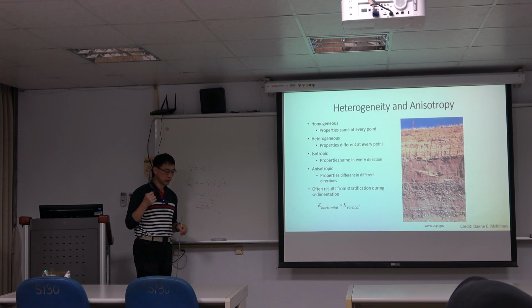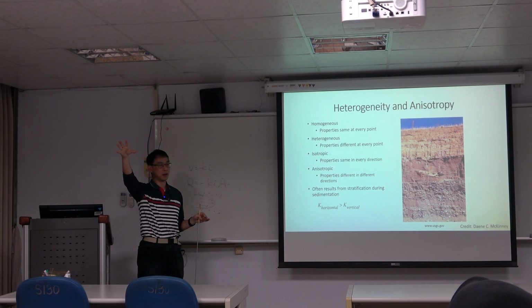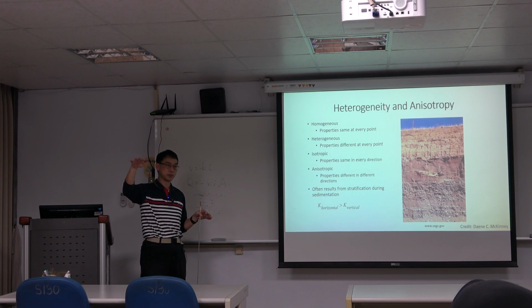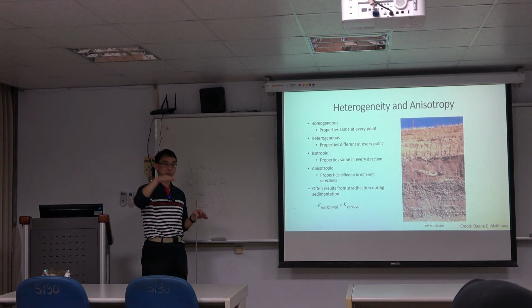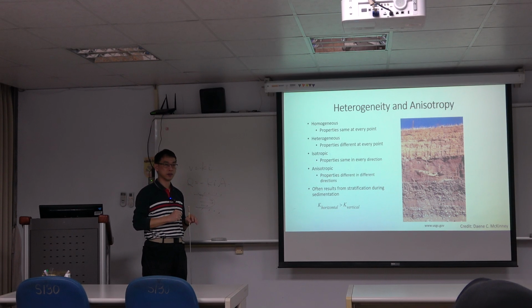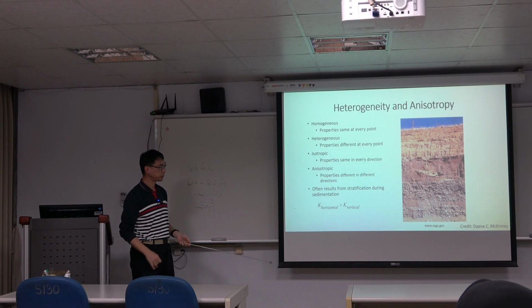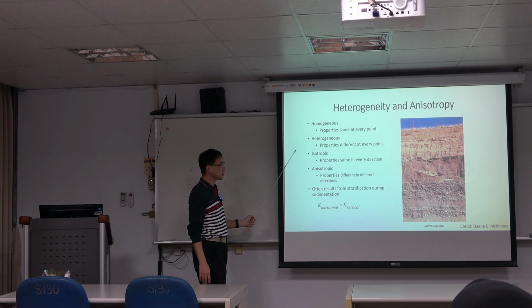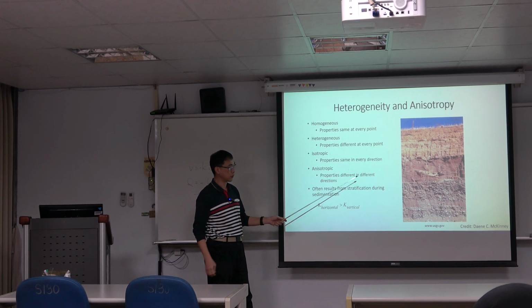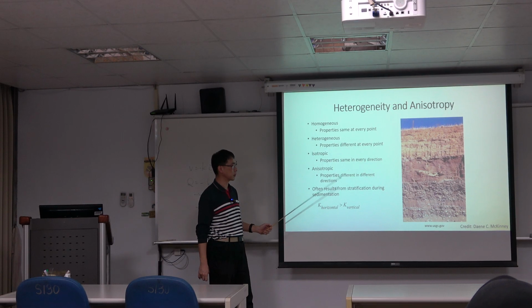For example, in an alluvial fan area, commonly larger grain sizes deposit in the proximal fan, and then the middle, and then toward the distal fan they become more fine-grained materials. Although it is the same system doing the deposit, right, the grain size distribution will be different. So your hydraulic property will be different. They are the same formation, but they have different hydraulic conductivity. So be careful about this issue. Heterogeneity commonly exists in natural systems, although at a small scale they may be relatively similar.